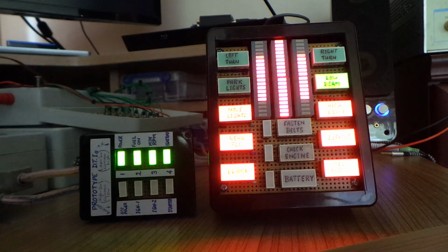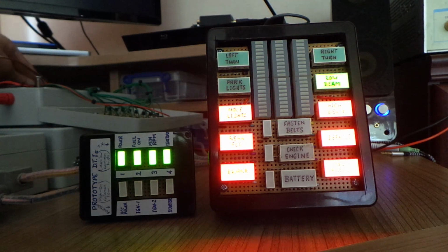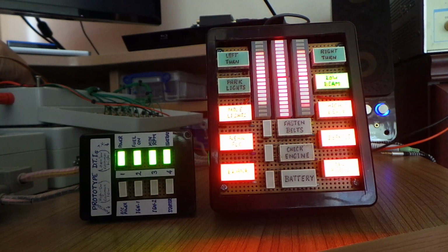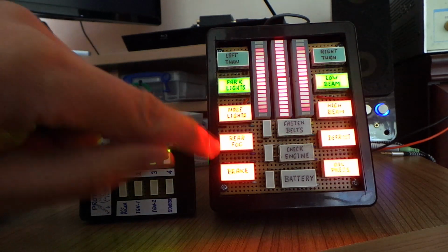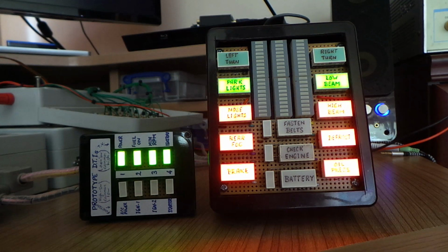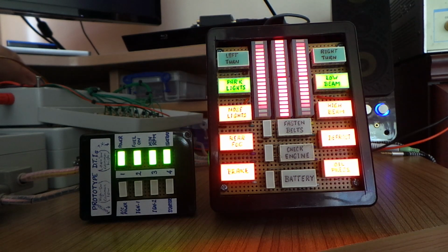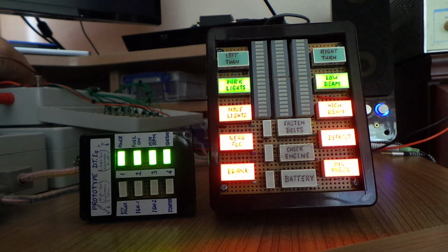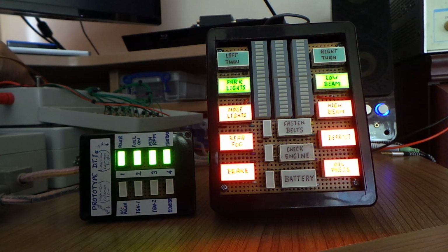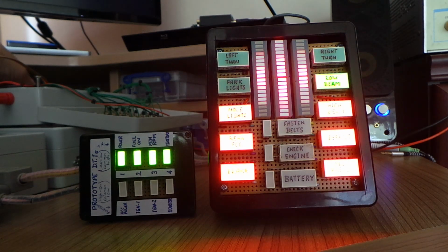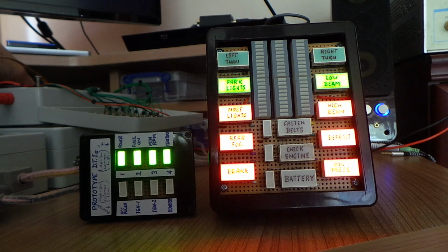Now look what happens when we put the park lights input on, and this is connected to the park lights or the headlights. This is a user option as well. When you switch the lights on, it enables you to dim all of the other side indicators. That's not clearly visible on this display because the camera tries to adjust the brightness, but take my word for it, as the park lights are switched on, we can decrease the brightness of the side indicators.